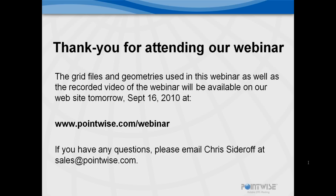A third one that I would mention is that it is much easier to get a repeatable mesh character when you're looking at case studies, for instance, for different changes in geometry. You want to compare results in a design study. You want to compare results on equivalent meshes so that you know that the changes in flow properties that you're seeing are not due to the changes in the mesh. This is a notoriously difficult thing to achieve with unstructured methods because an unstructured method builds itself up every time from the boundaries and is not quite as reproducible as a structured mesh. So that's another reason: when you're doing a design study and comparing results across different designs, a structured mesh is going to give you a better comparison.